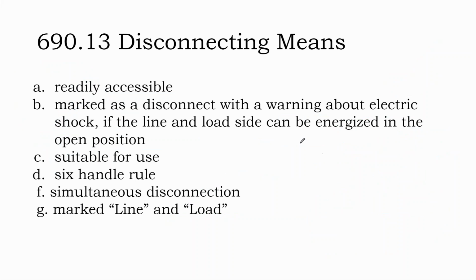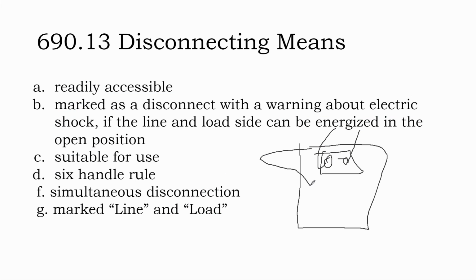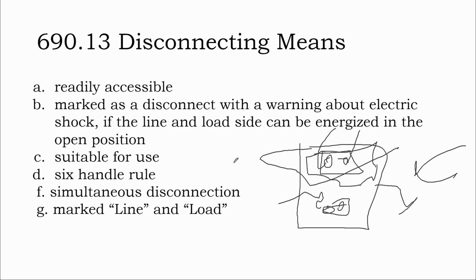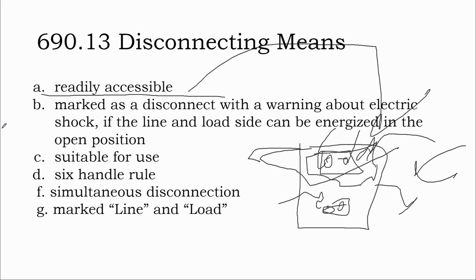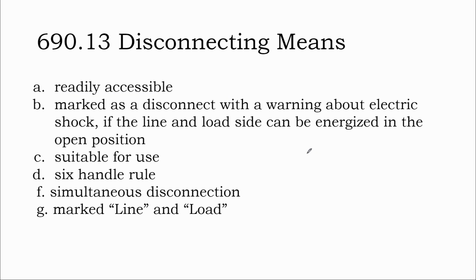An electrician is comfortable looking at these terminals energized from the top, but still nonetheless opening up the lid to that disconnect switch and maybe even working on the underside of the switch away from this energized area because they know what they're doing. Someone else could misinterpret this switch being down as off and this lid being open to reach in and touch those terminals because they want to do some amateur wiring work and electrocute themselves. And that's why these readily accessible disconnect switches need to be locked so that only people who should be in them can get in them.